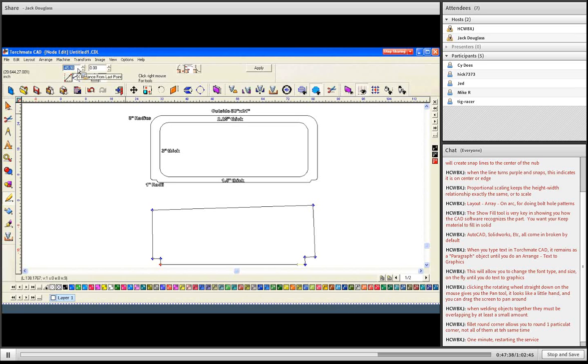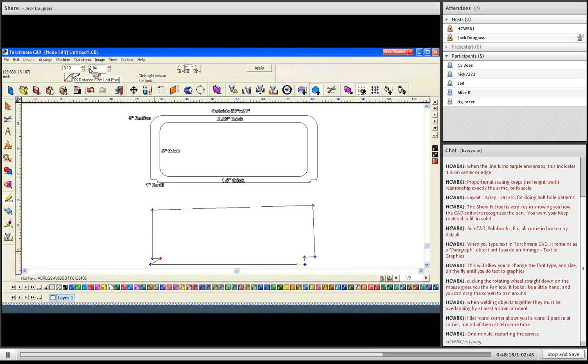And for the distance that we need it to move, if I recall, we came in 2 inches here, I believe. So 2 and 2, so 49 total for this bottom section. So we'll go minus 49. I'm not worried about these other ones not moving yet, so we'll go to the next node. I can either click on the next node, or if I'm not sure what the next node is, I can stay at that node, press tab, and it tells me where it goes to the next node. Right now, it's saying that it went right 3.1 inches and up 1.84 inches.